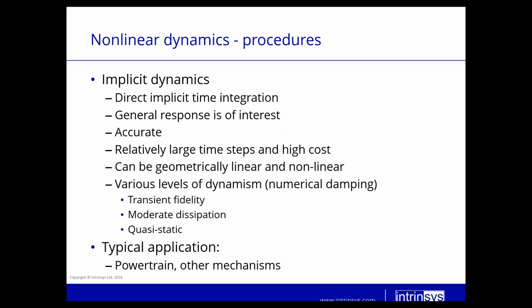This is an accurate method, as it's unconditionally stable, and it can take relatively large time steps. It takes fairly long to solve. It can be geometrically linear or nonlinear, and you can include various levels of numerical damping in your solution.